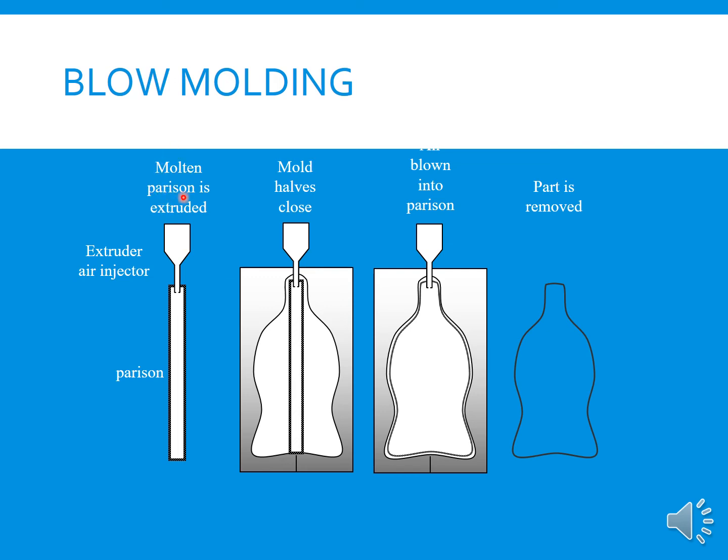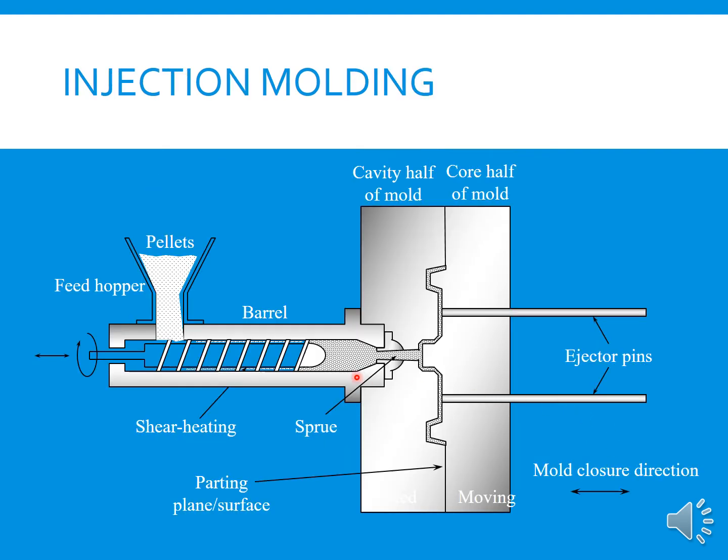Blow mold. Okay, this is blow mold. The first step is making the parison by extrusion. Okay, from the nozzle, you inject the material inside here. Okay, the material is like this one, and then we transfer and move the parison inside the mold here. Okay, it is already hot. And then we put it inside the mold, the mold shape. Okay, and then we close the mold, and then you use air to blow the parison, and the material will open up here and expand, and after we complete the shape, we open the mold, and you get the part.